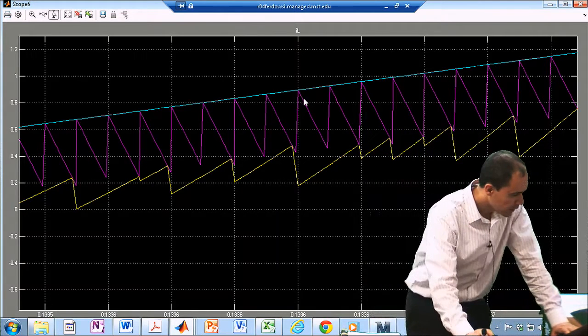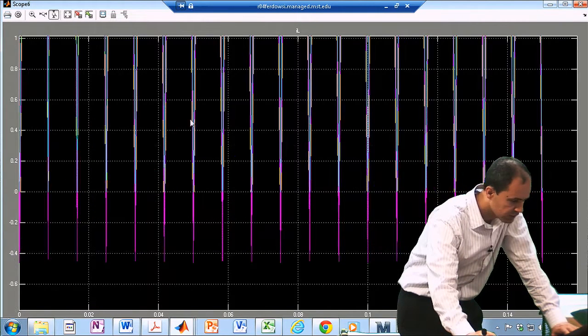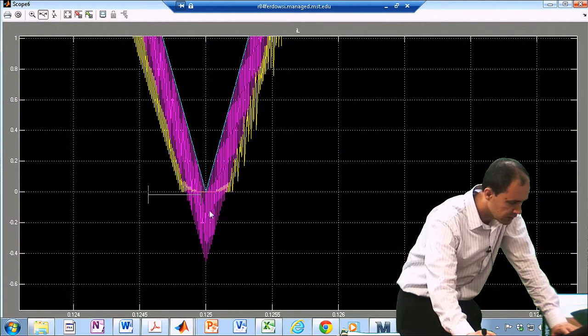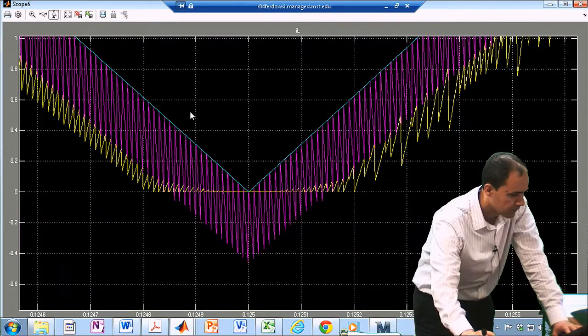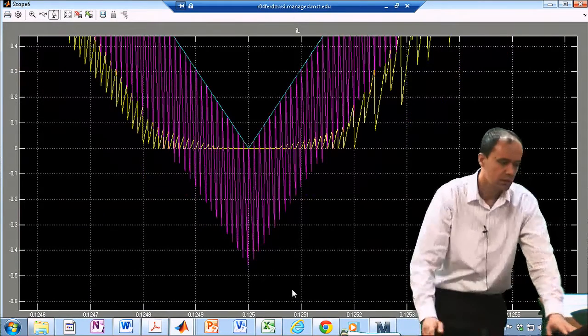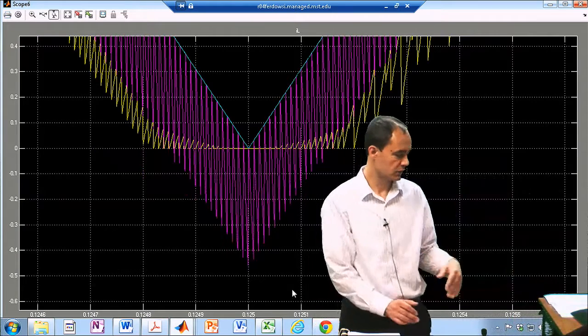All right. Also, as I talked about a few minutes ago, when we cross 0, you can see basically what's going on in your signal. Your reference is very small. Then you subtract the external ramp from it, so you can even get to negative territory.